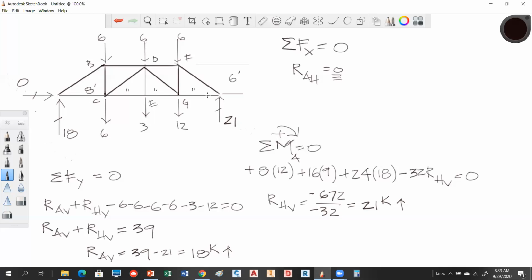So another way of stating that, Jacob, would be to say that you have 4 panels at 8 feet. So this could be a panel, panel, panel, panel. When you're saying 4 panels at 8 feet, you're saying they're all the same, they're all common. But that wouldn't be true in all trusses. You could have like 8 feet, 10 feet, 10 feet, and then 8 feet. So it just depends on the truss design. Yeah, good question. I'm glad, I just kind of assumed everybody knew what I meant, but that's good.